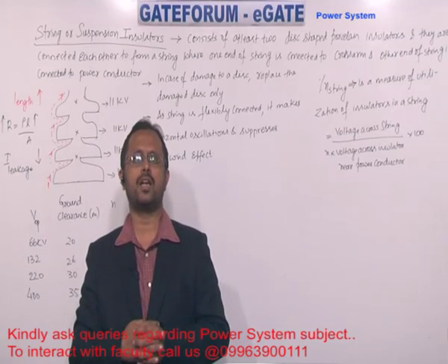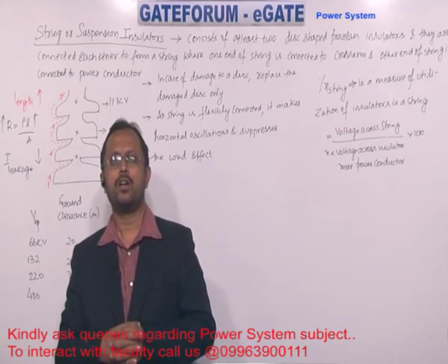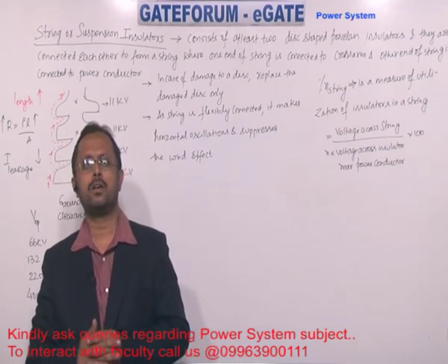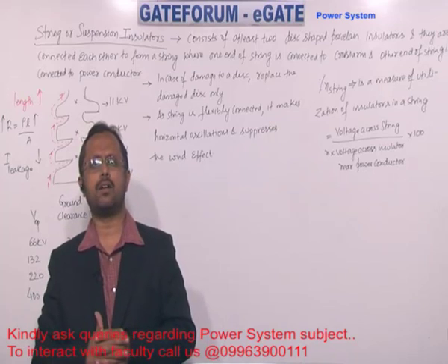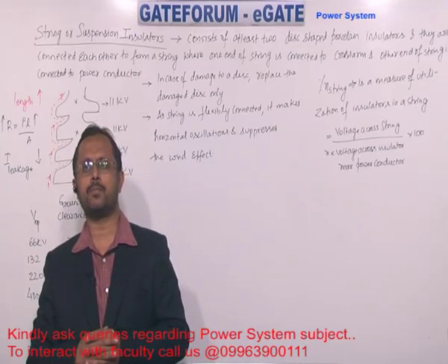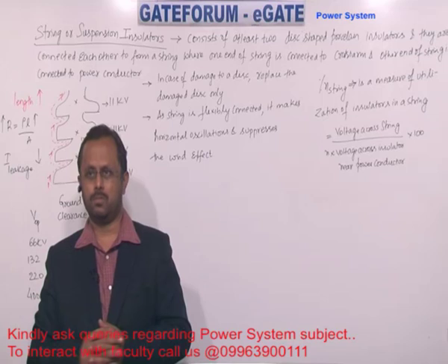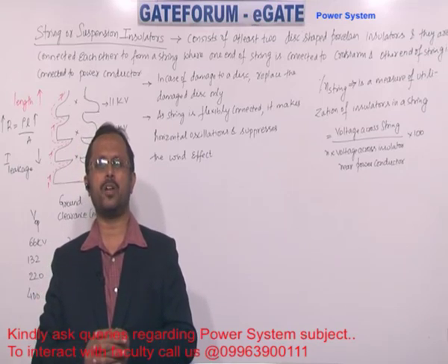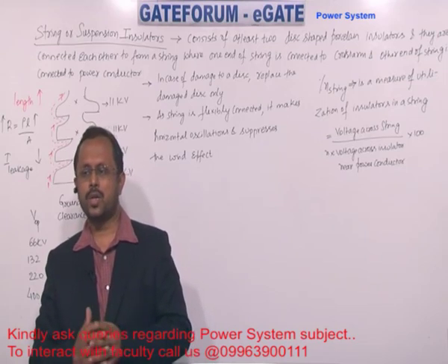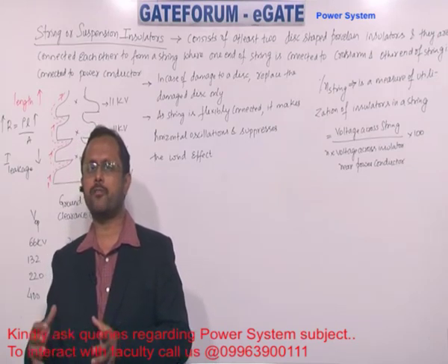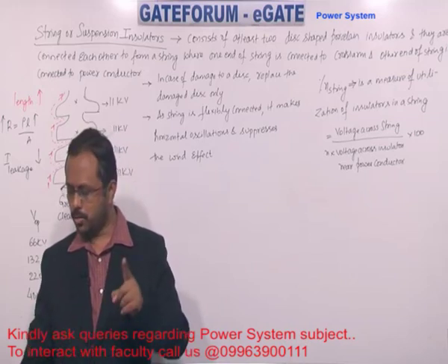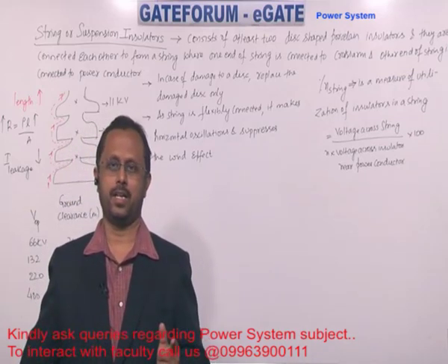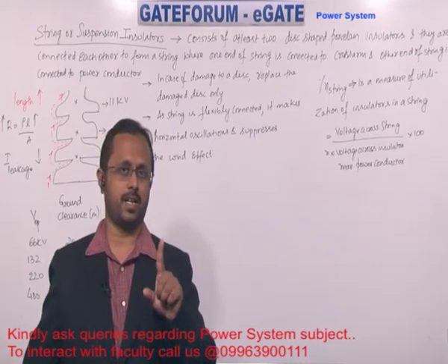Next question is by Shailesh from Bikaner. Two-phase system is not practically used. Why? Is there no existence of such a system? No, a two-phase system we never use, please. Due to drastic changes, we made from single phase to three-phase. In two-phase, there is the disadvantage of the 90 degrees phase shift, not 180.